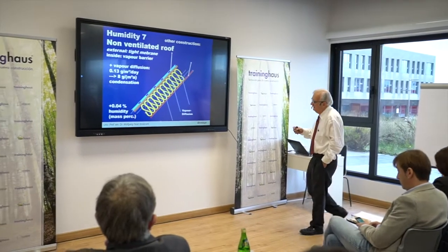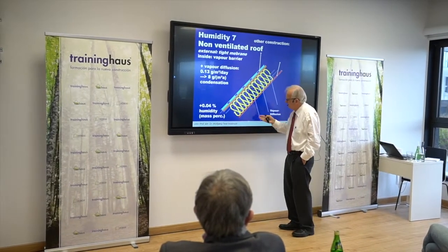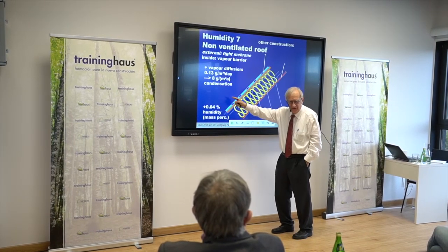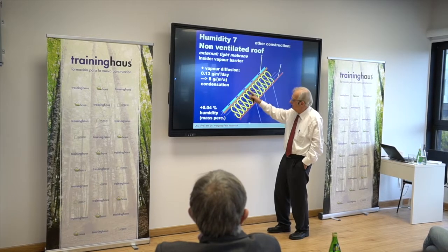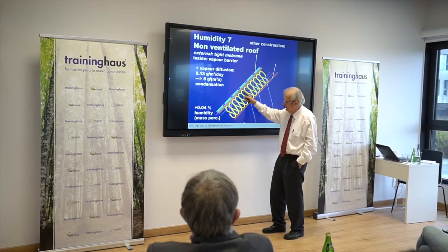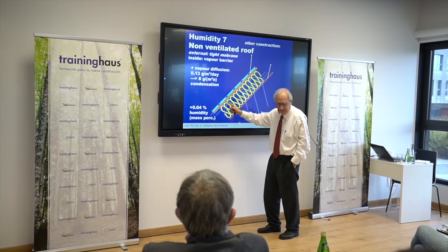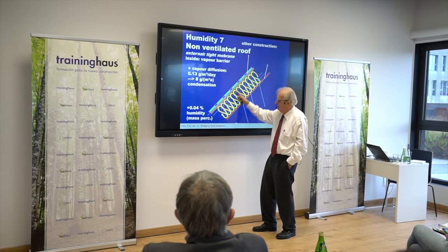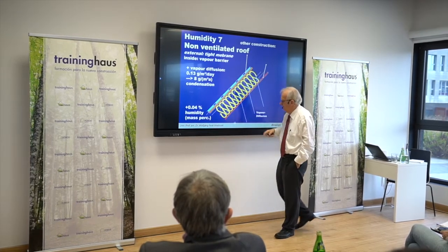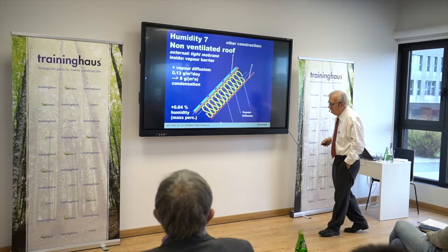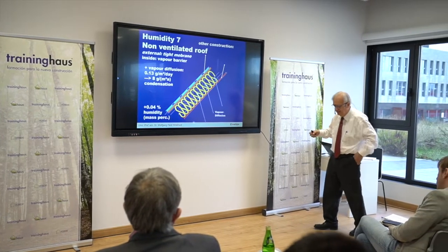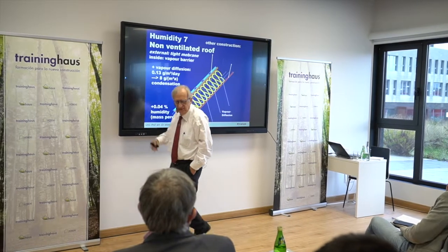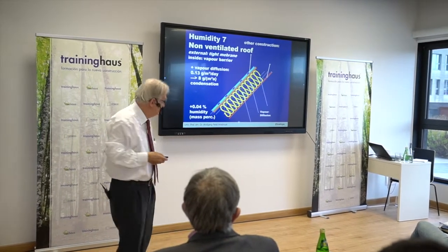Because now, even the water vapor which comes into the construction due to water diffusion cannot be ventilated out on the outside because it's tight there. And of course this layer is cold during winter. So you definitely, from time to time, would get a higher humidity on that layer. Yeah? It's not avoidable. You get that. But the question is, how high would that be? And at the end, of course, during other periods of the year, during the summer, it can evaporate again. Of course, then to the inside. And these things can work.